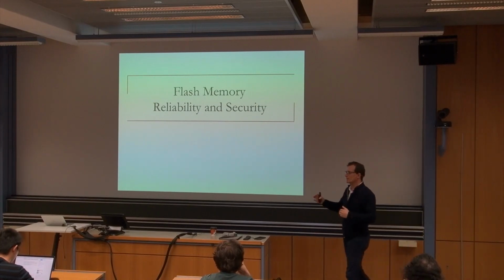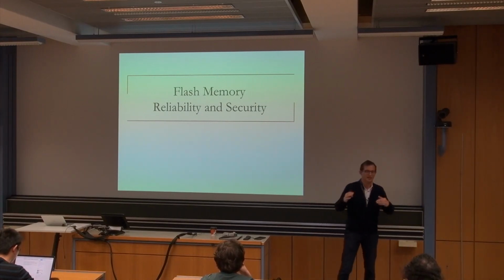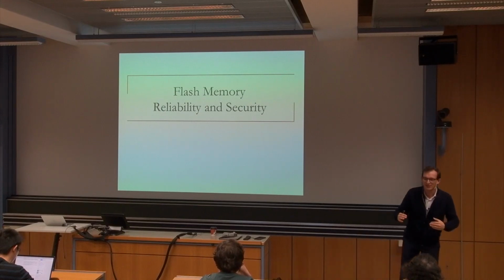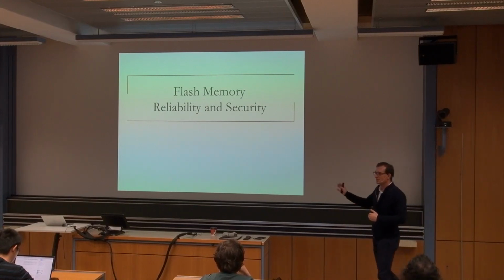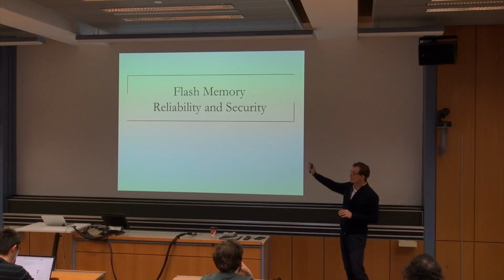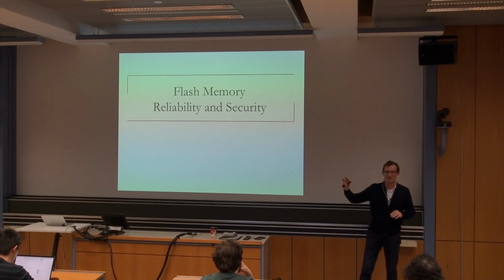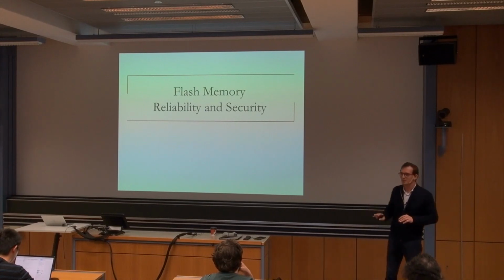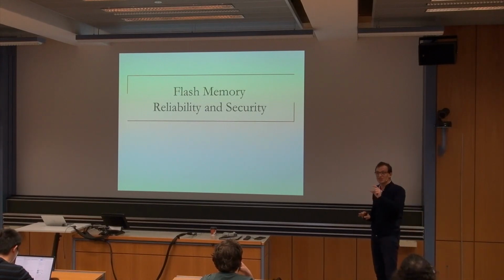And this is a trade-off that was made for cost reasons, because erases are actually extremely expensive. As a result, flash manufacturers said, we're going to do erase at the block level. And as you saw, blocks are 256 pages, right? And you do erase at the block level, but you want to modify only that page. Now you have a problem. You read the page. What do you do?